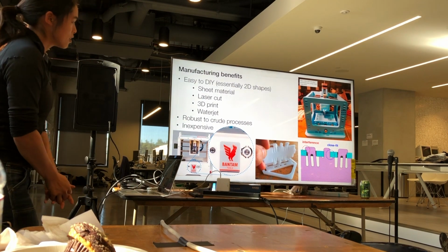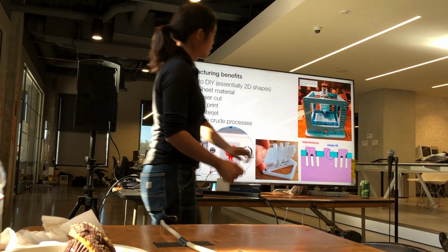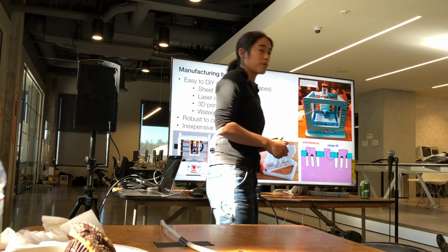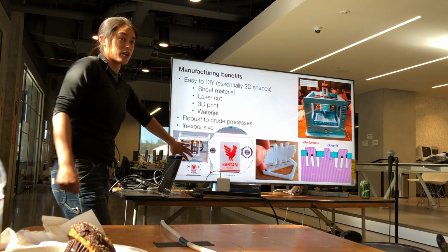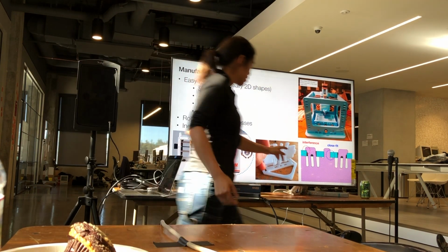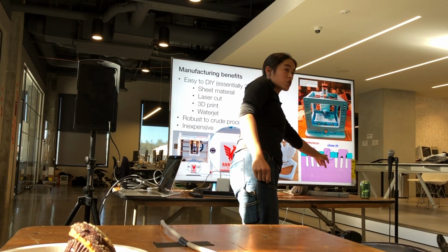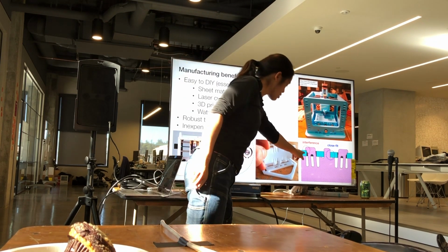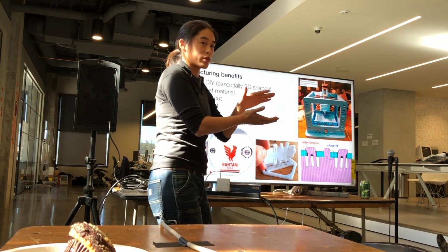Here's another one of my favorite examples of how it's robust. This was a snap lock mechanism that I first learned about from the MIT machines that make snap lock thing, and I think the ideas were later applied to the other mill. So here you can see this feature is used as a close fit locating feature, and these two arms here are flexures that, because I've designed in an interference, apply a load that's compressing the joint together.